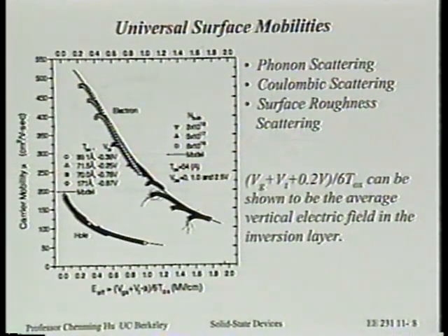I want to ask you a question about this 1/f noise, buried versus surface channel. Maybe you can share experience with this. Is this something you have some personal experience with, or just something you heard? No, for me, it's personal. All right, great. So you had a choice of using so-called N plus poly and P plus poly device. Is that right? Right. All right. How much difference do you see in the 1/f noise? It depends on the generation. Factor of 5, factor of 3. Okay, that surprised me a little bit. It's that large. I thought maybe less than that. Certainly 2 would be very understandable, but 5 sounds surprisingly large.